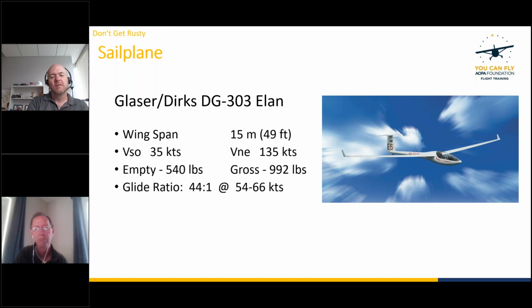For example, European aircraft are certified with a maximum seat load of, I believe, 240 pounds. So it's not about how much you weigh. There are some gliders that can carry people that are heavier than that. It's a function of what the certification limits are on the glider. Most of the gliders now are European designs, and they have a certification limit of the seat weight, which is why you're taking a little bit of grief on how much you weigh. They can't legally carry you if you weigh more than that in the aircraft.